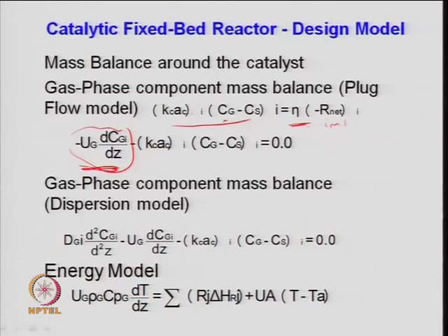If mass transfer is the controlling step, then the rate is given by K_C a_C times C_g minus C_s at the surface. It is something like a non-porous catalyst pellet, where you have a concentration in the gas phase and a concentration at the surface. So, we can do it for monoliths also, or any non-porous solid catalyst, right. The expression will come like this.